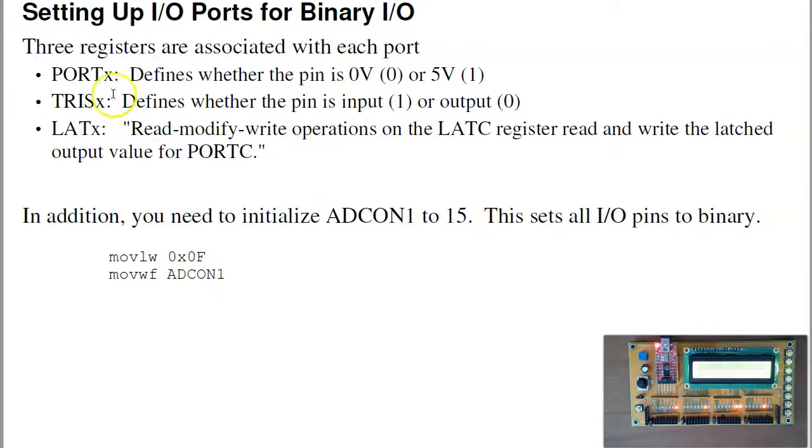The other ones you need are the port. That defines the pin. 0 is 0 volts, logic 1 is 5 volts. There's also TRIS. That tells you whether you're input or output. 1 means input, 0 means output, and a port is 8 bits.